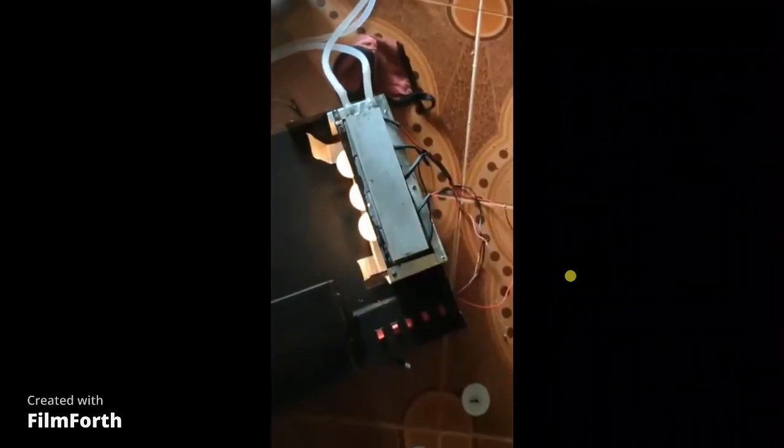This is our final output, where we can see that there are candles at the bottom and a heat sink above the candles, which will be used as the heat source, and above that there is an aluminum chamber that will store the cold water. The cold water is supplied from there, and there is a suction motor which sucks the water and transports it to the aluminum cold water chamber, due to which there is a temperature gradient. There is a hot chamber below, and above that is a cold chamber. Between them we have Peltier cells, and due to the Seebeck effect, electricity is produced.